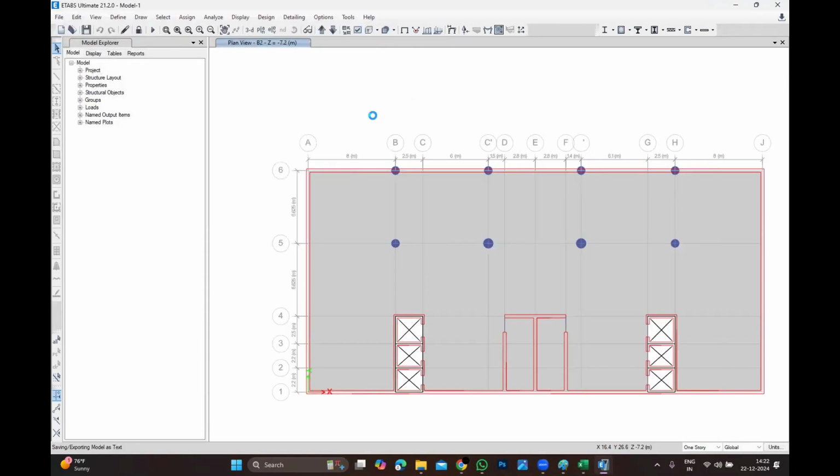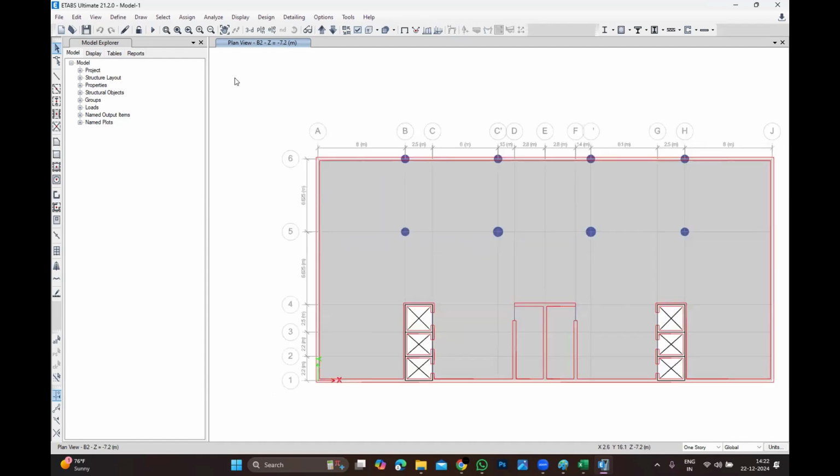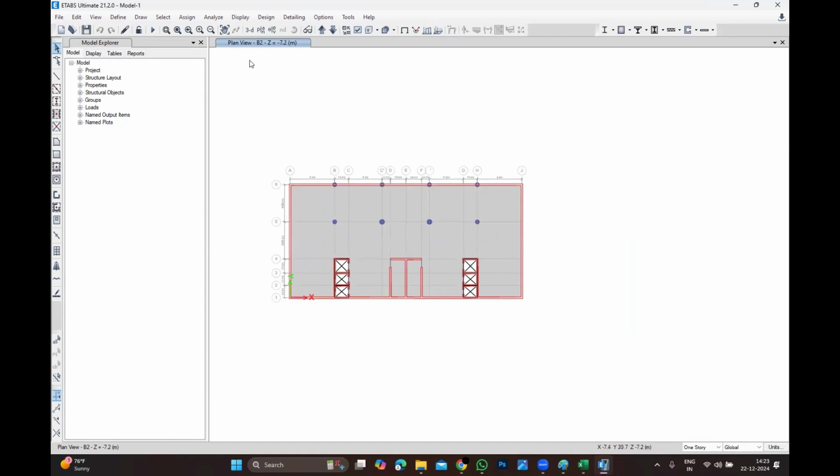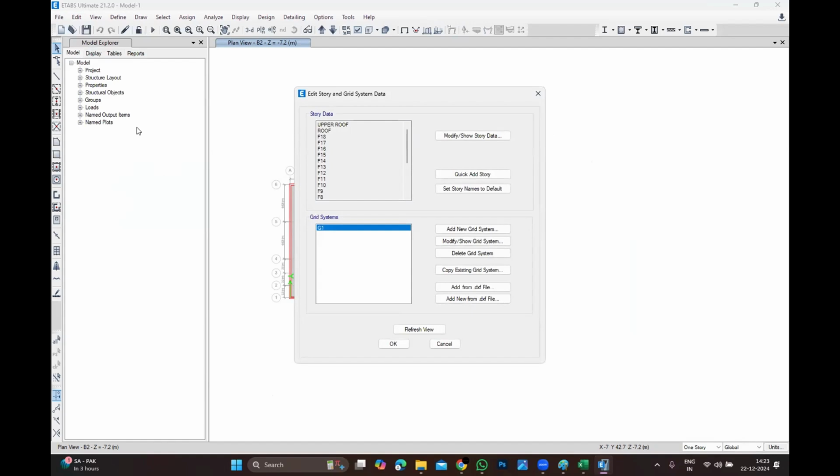Give a different name. Except basement 1, on the basement 1 slab just apply the new 1 kilonewton per square meter SDL. A 1 kilonewton live load is huge. Okay, I'll tell you.